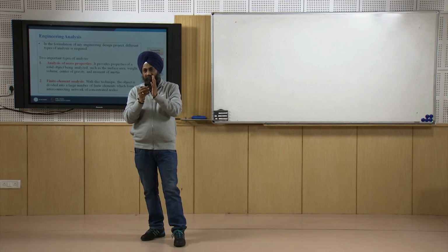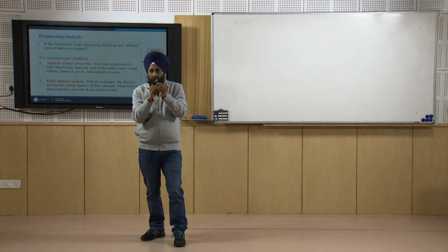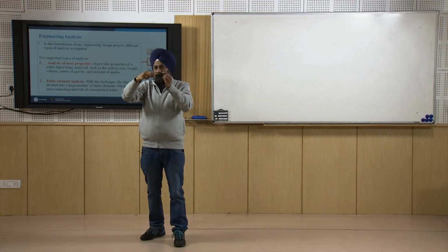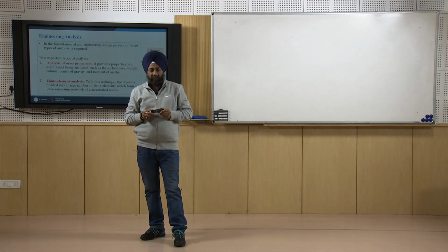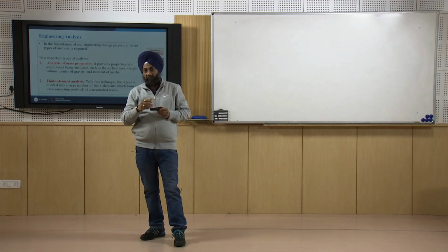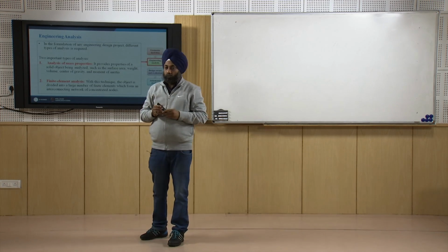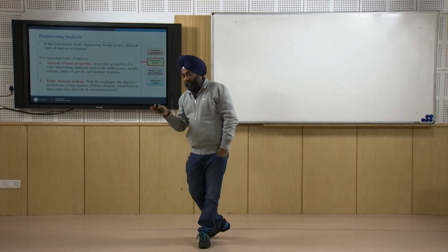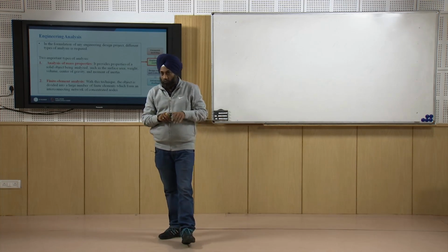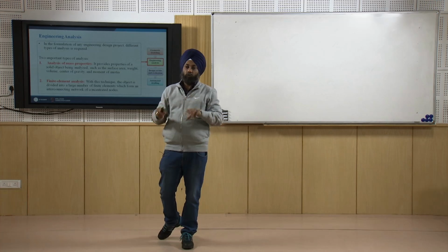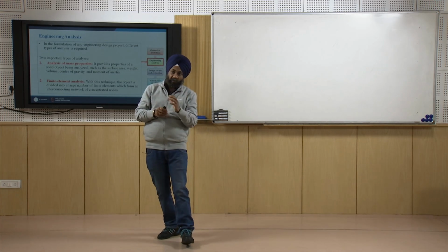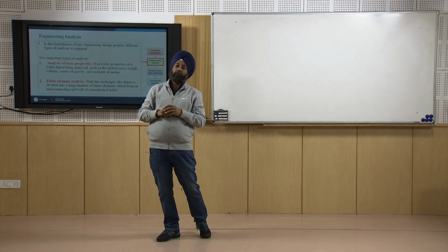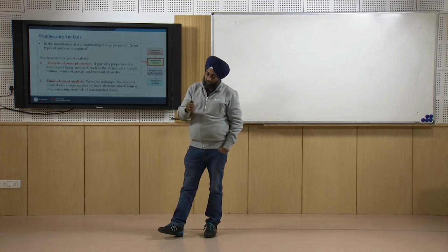We can model that, divide that beam into the individual components, apply a load here and see how it will deflect, what would be the maximum displacement, or what types of stresses are being developed on the application of load. So those types of problems can be solved using finite element analysis, everything on your computer screen. So CAD these days is not only related to drafting, but it can be combined with the analysis procedures also, and can give us a complete design of the product.